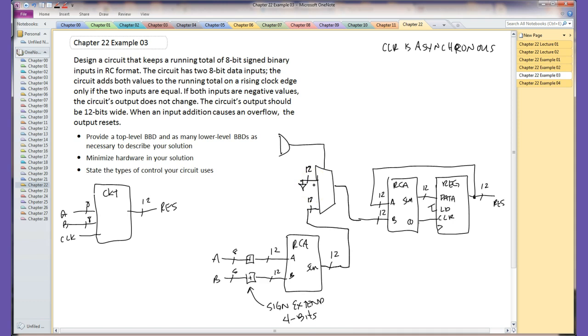There are two other parts to this problem. One is the numbers have to be equal, so I will drop a comparator in there. We can make an 8-bit comparator. There's our equal. The last thing is these numbers have to both be positive, which means the sign bits on these numbers have to both be 0.